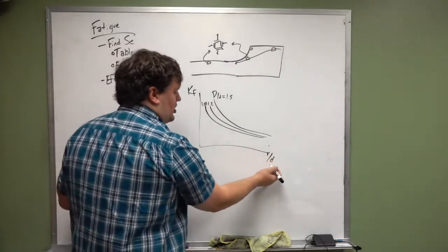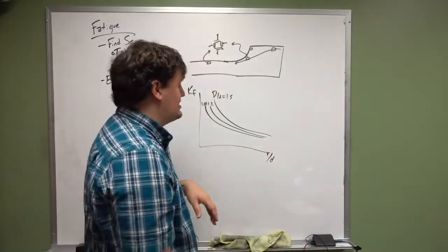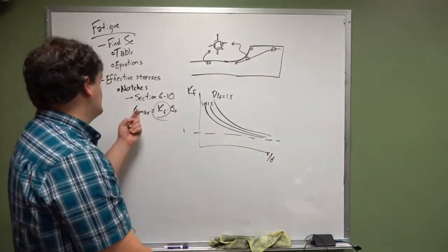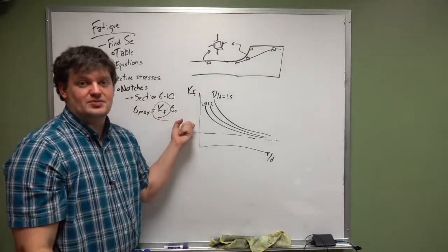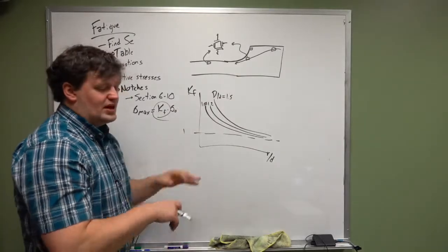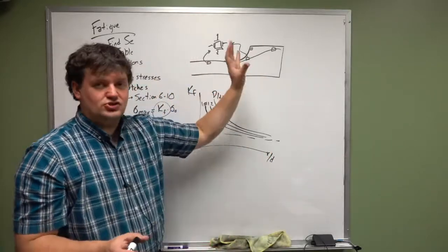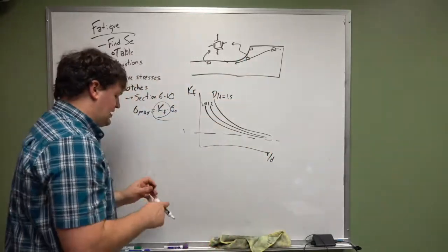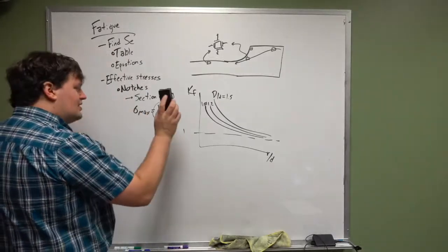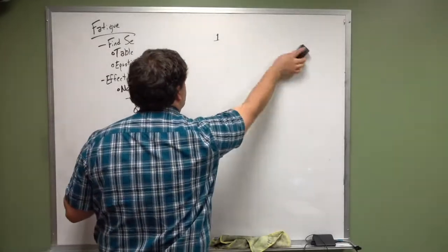You'll notice that as r over d becomes greater, meaning you have a larger radius, this really approaches 1. Which means that the sigma max is equal to whatever your sigma max value is that you calculated before taking into account your notch. Okay, so having stress concentrators is important, and you do need to understand that geometric changes do cause stress changes. That is also very true for fatigue. So this is a modification of what the stress is. But we may have a different situation entirely.